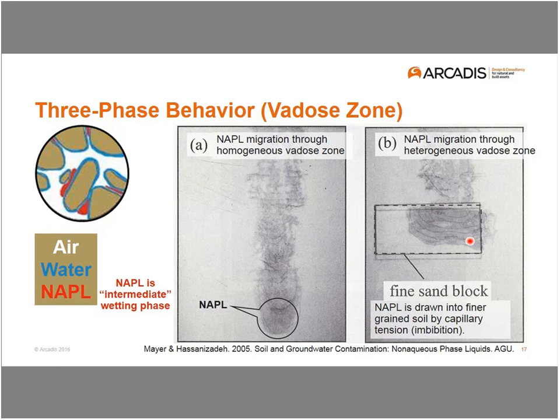So it's something to think about when you have a situation where the LNAPL has distributed itself either in the vadose zone or you have large water table fluctuations, maybe going across different grain size zones, that when the LNAPL is above the water table, above the top of the capillary fringe, and it encounters a finer grained material, that LNAPL will imbibe into that fine grained material. And that could have real implications for what you're going to do to remediate that LNAPL.